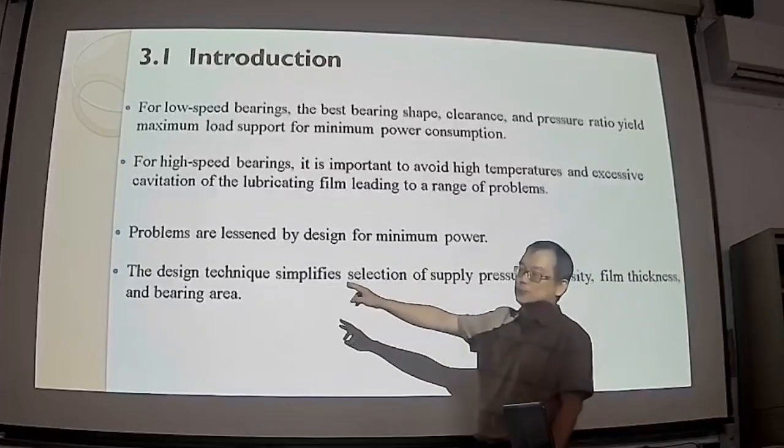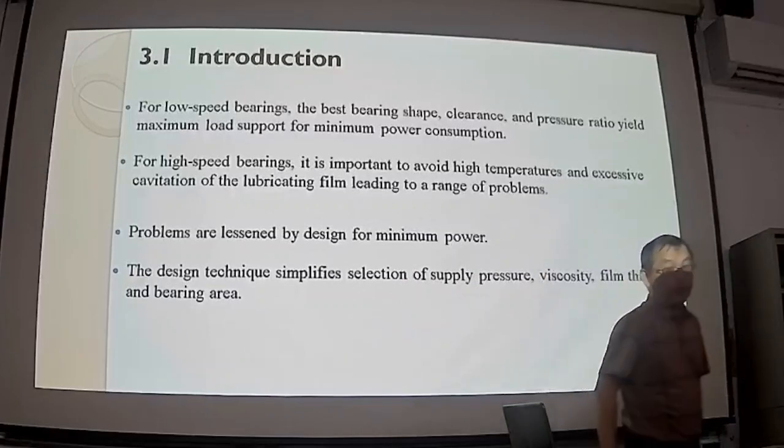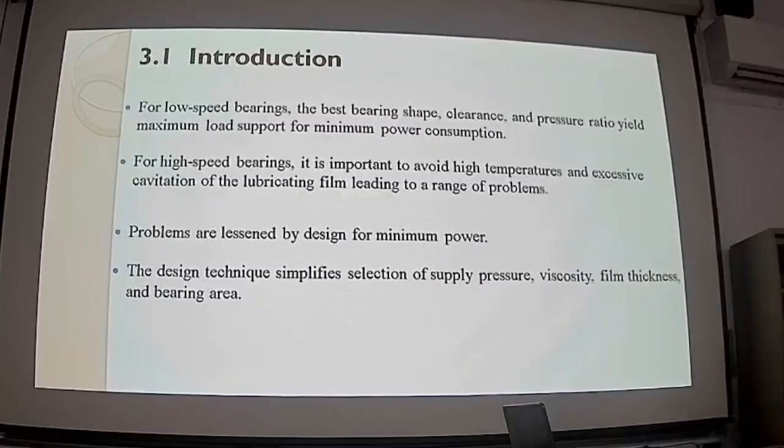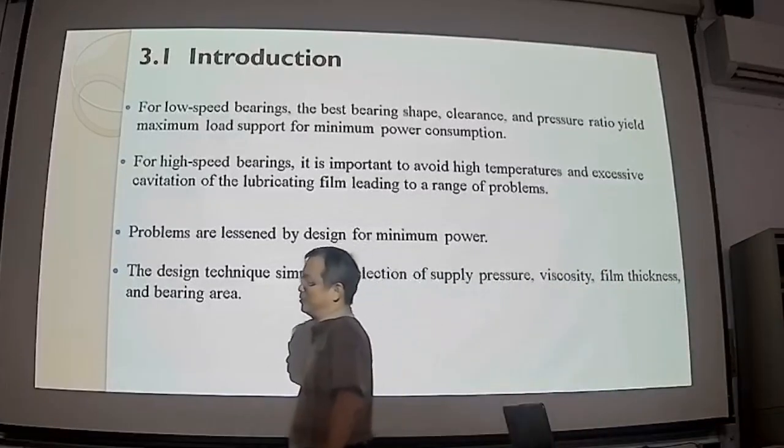And for the supply pressure and the bearing head area, these two will be decided by the load capacity you need to carry. For example, for your slide table, you need to hold a workpiece of 20 tons, and then you have an extra cutting force. These two added together are your maximum loading for your bearing.